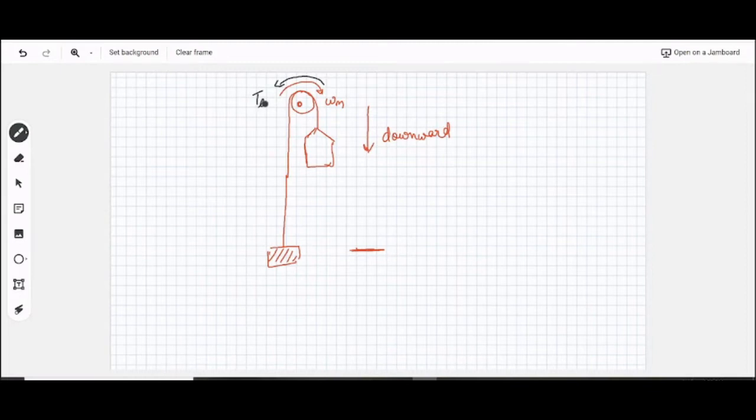Yes, sir. That means to bring that down, your motor has to produce a torque in this direction, in the direction of the motion. Now see, because your motor torque and the motor direction of rotation is same, that concludes that drive under this mode or under this operation will be in motoring mode, right? And as we are bringing it down, the rotation is such that it is bringing the lift down. We'll call it as reverse motoring.